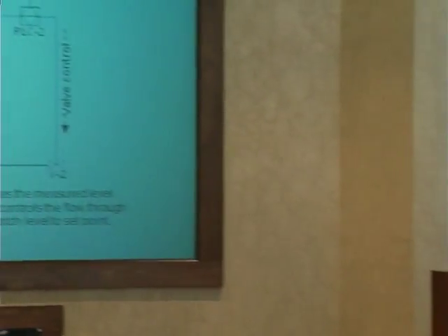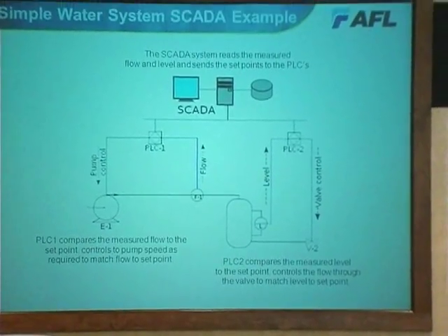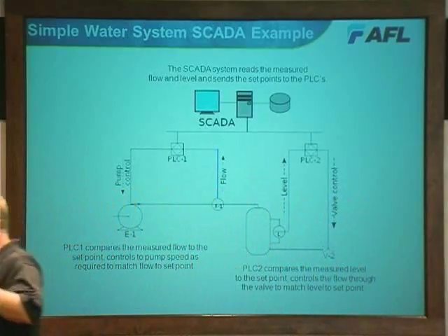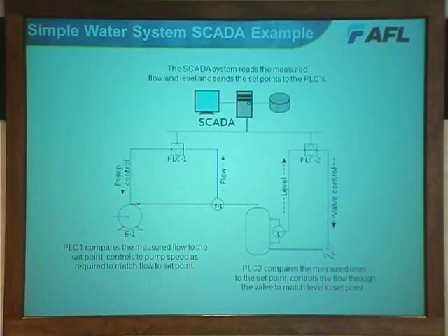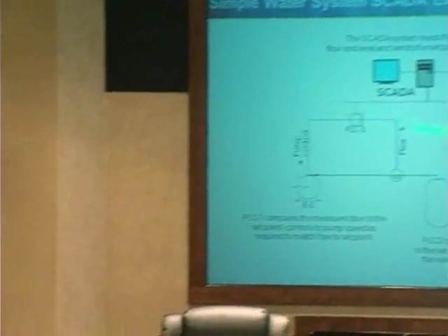All right, so here's your first diagram of the day. This is a water system. Just think about this closed loop system that we talked about earlier and how we can control and look at the different parts. You've got the SCADA program running up on the computer. You've got these programmable logic controllers, or what's another name for those we've already mentioned this morning? RTUs. That's where your distributed intelligence is, in these programmable logic controllers.